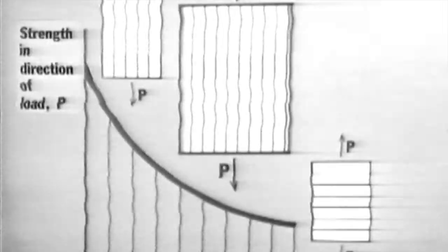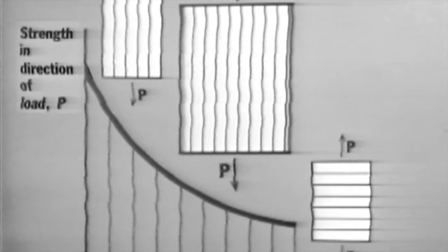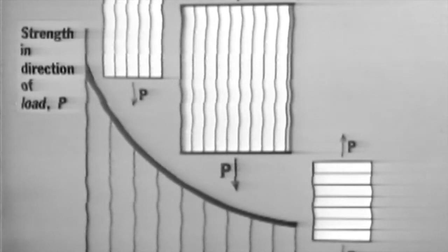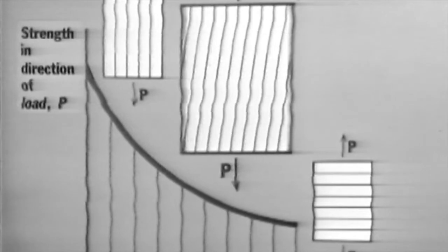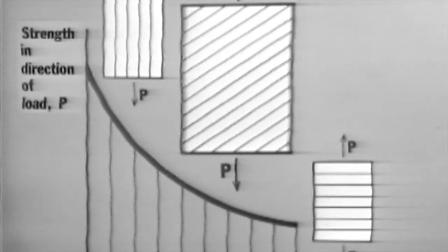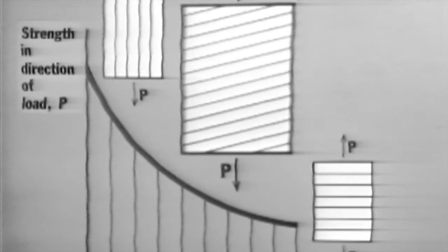Since the filaments are narrow compared to their length, they are in need of support. The matrix provides this support, and the filaments in turn provide strength to the matrix. Because of their very nature, filaments in a single layer must be aligned in a parallel arrangement. This is illustrated in the following figure. Here, strength is plotted against orientation angle. The reference direction is the axis of loading.